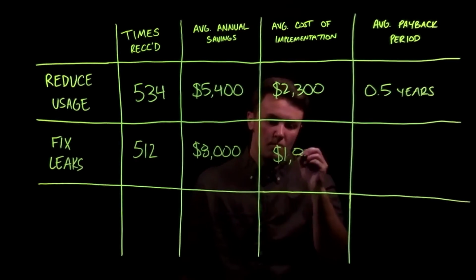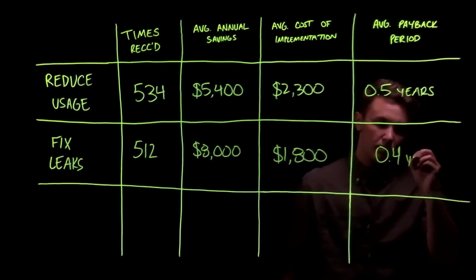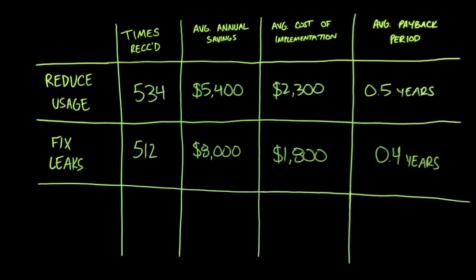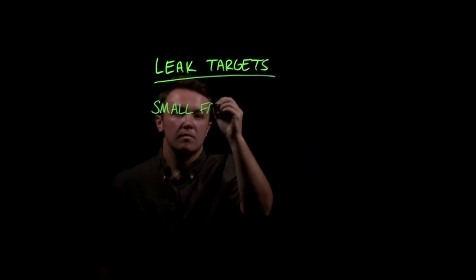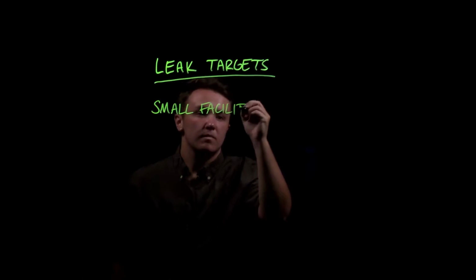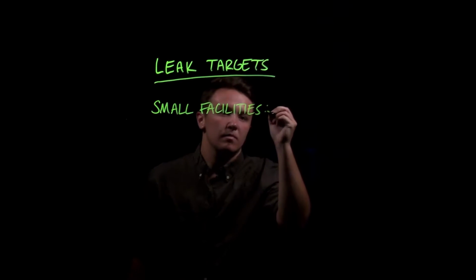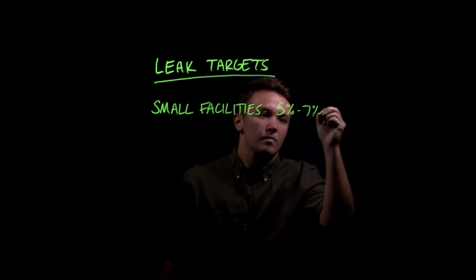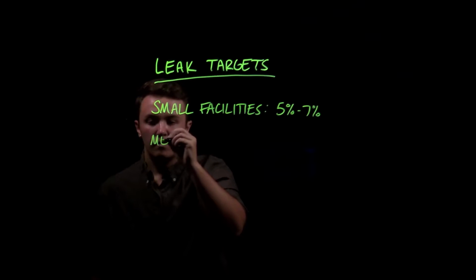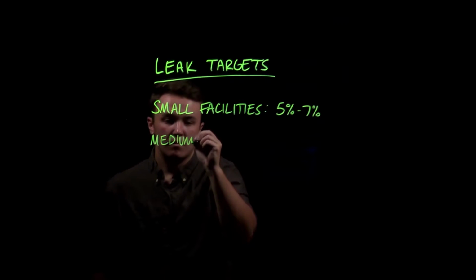The next recommendation we will talk about related to compressed air is to eliminate leaks in the system. This has an average annual savings of $8,000. If you have a compressed air system that has not been inspected in the last 3 months, consider inspecting it and implementing a quarterly leak detection program moving forward. Fixing leaks once is insufficient because leaks develop continuously, so having a regular schedule to perform maintenance is key.